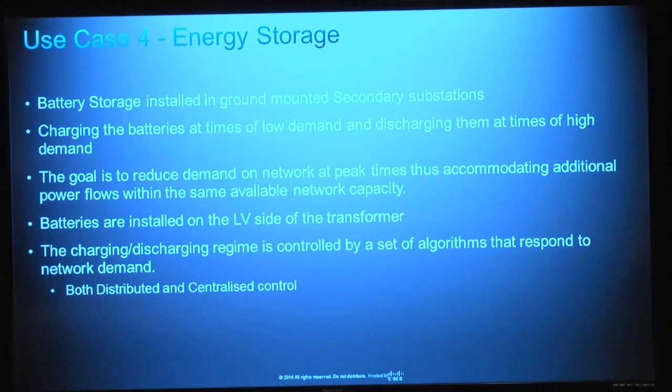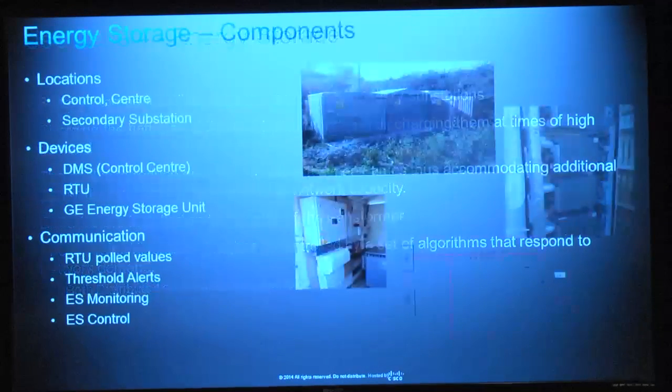Distributed control, centralized control was available to those battery controllers, but predominantly it was being run out of the distributed control model where the controller for the battery itself was making the decision to begin either charging or discharging accordingly based on the measurements in the network.